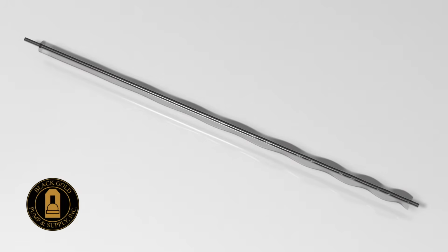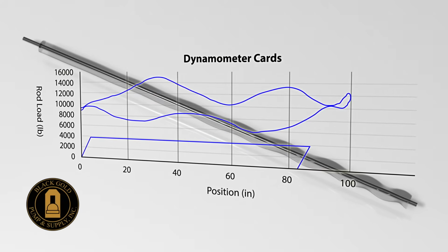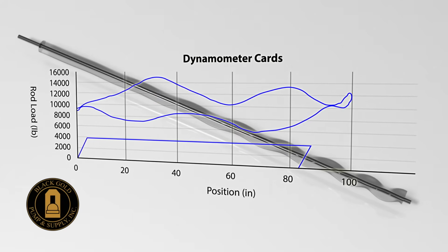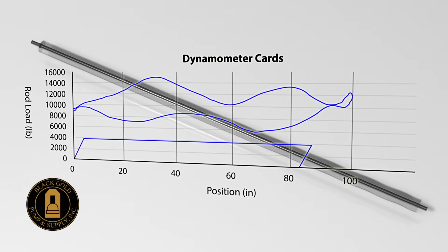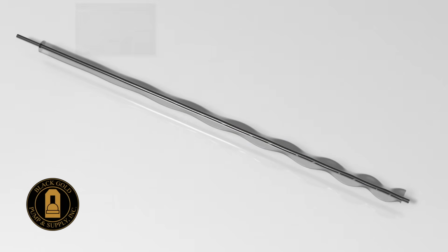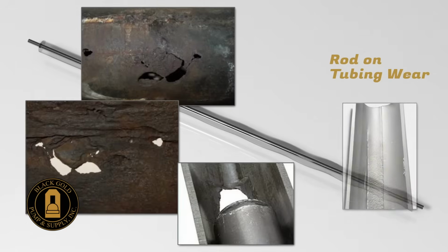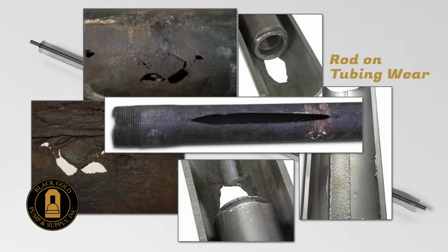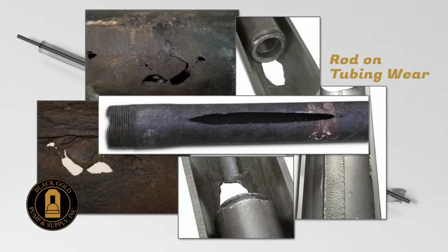Why do we anchor tubing? In the 1950s, Arthur Lubinsky detailed the phenomenon of production tubing buckling during the upstroke of the rod pumping system. This buckling of the tubing has a detrimental effect on the production efficiency, as part of the pump stroke is wasted, contracting and stretching the tubing rather than lifting the plunger inside a stationary barrel. Also with this tubing buckling comes increased rod-on tubing and tubing-on casing wear.